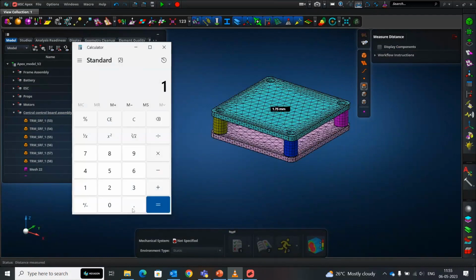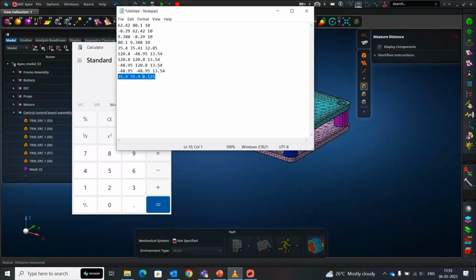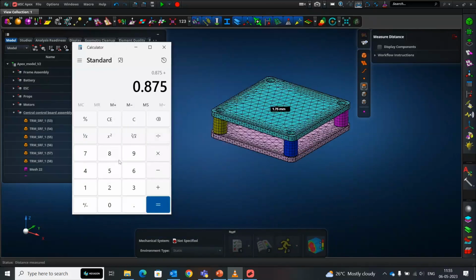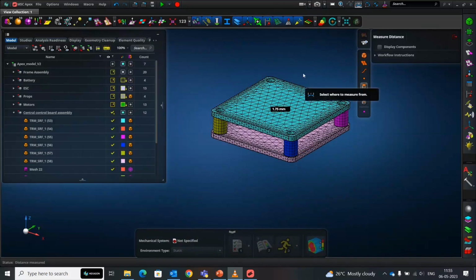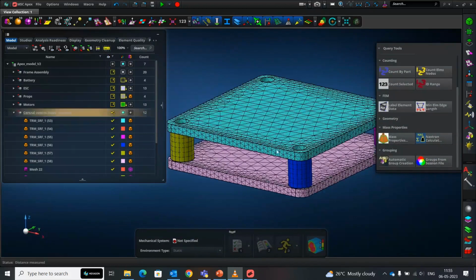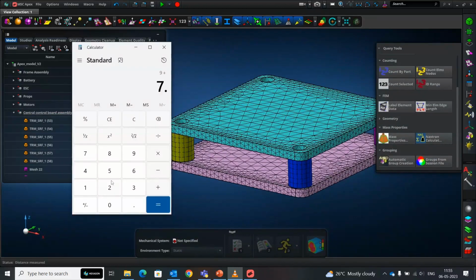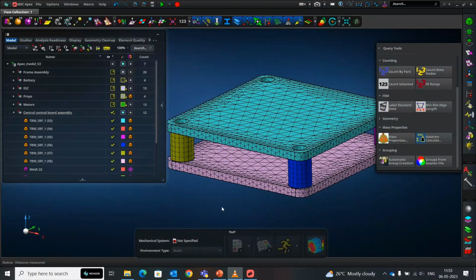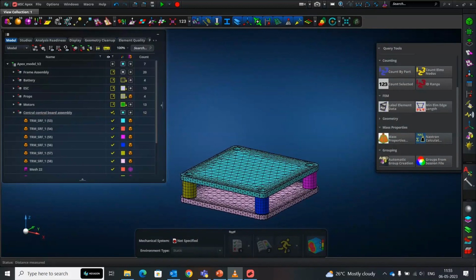It's 1.75 millimeters. With that, I'm able to find the midpoint thickness, add that to the CG location of my choice, and I know that it's going to be 9 millimeters from the top surface. I'm going to take that, and then I know where my CG location is going to be for my individual board based on the dimension of it. It's just any generic board. These are all just basic geometrical computations I'm doing.